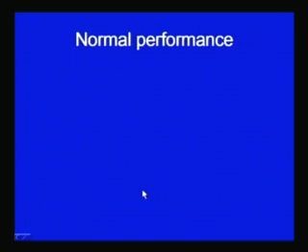Now, this is another important point related to the time study: the performance of the operator is rated during the study, and that performance is used for calculating the normal time. The observed time values are multiplied by the rating factor to find out the normal time. So, what is the normal performance, and why is it required to find out the performance rating of the worker? That we will see in detail gradually.